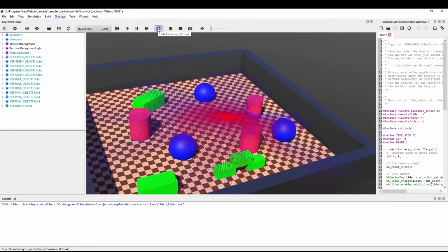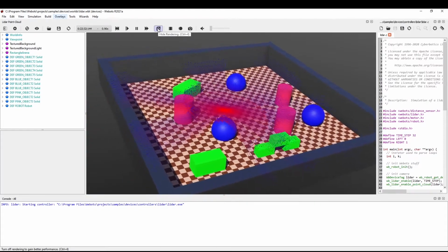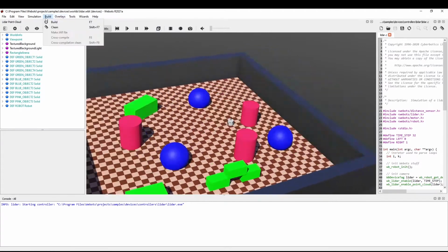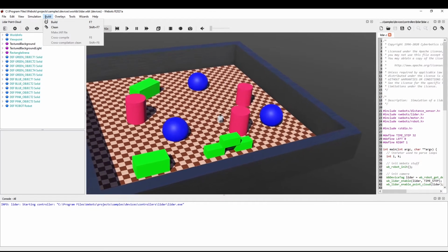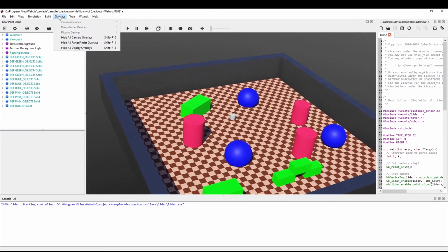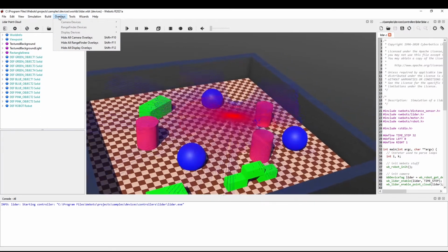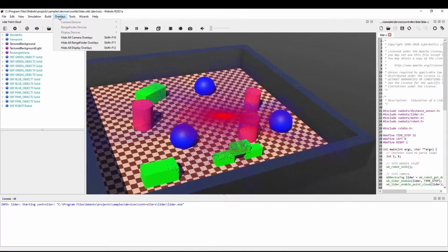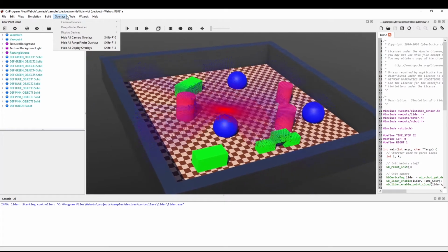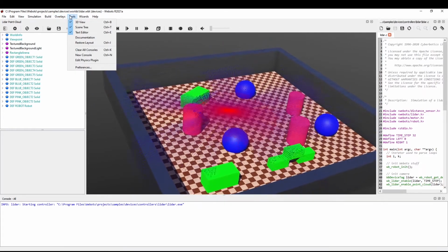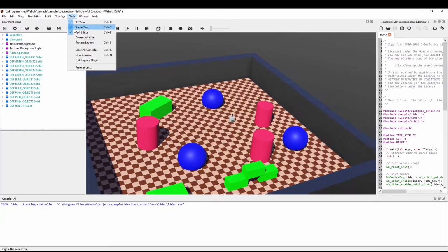This is the rendering menu item. The rendering menu item disables or enables the graphical rendering. The Build menu provides the functionality to compile controller code. This is the Overlays menu, which provides actions specific to rendering devices, if you need a camera, display, rangefinder, etc. Next is the Tools menu, which allows you to open or hide various Webots windows like the scene tree.